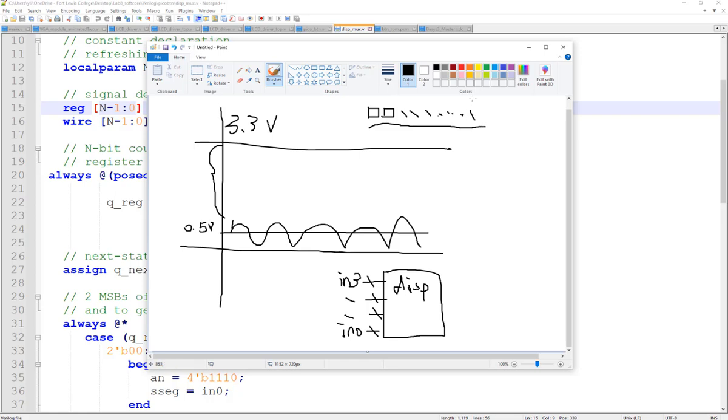Whenever it starts counting, it adds a 1 each time, and eventually counts up to 2 to the 16th for all these bits. After they finish the counts, this one gets a carry out, right? You get a 1 here. That should make sense. It's pretty simple because it has 18 bits: these are the 2 MSBs, and these are the 16 bits. It counts at 100 megahertz, flipping this LSB, and keeps flipping until it finishes all the counts here, and then it gets a carry out.